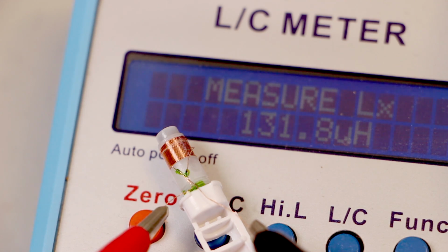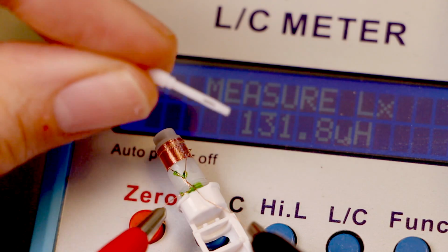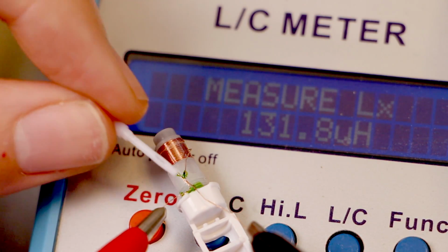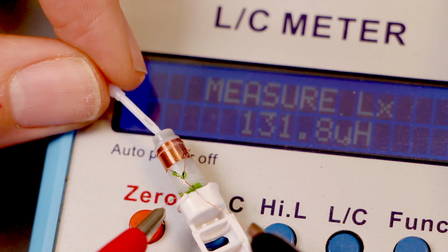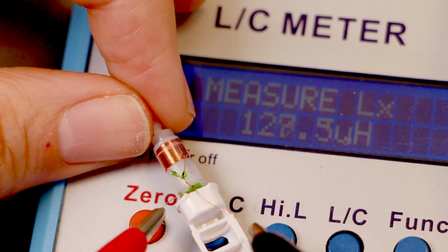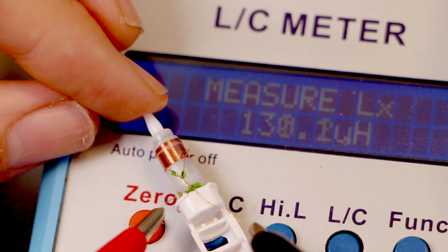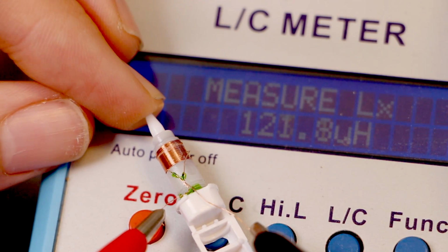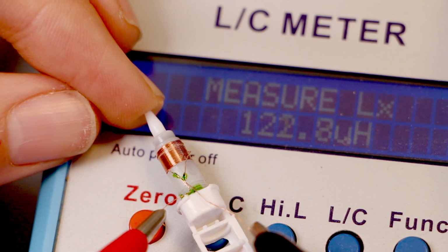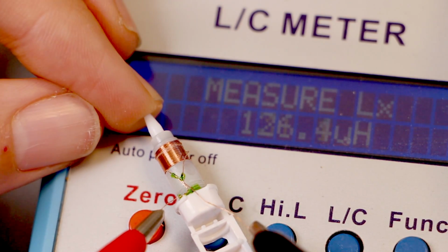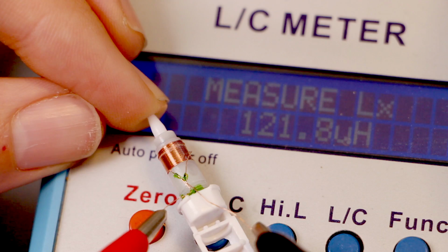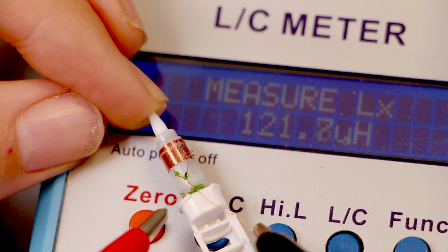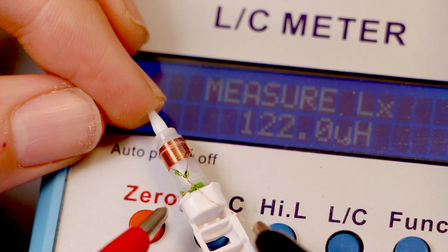Here I have the coil removed from the rest of the pen circuit and connected to a meter that measures its inductance. The pen nib itself is made of plastic and doesn't affect the inductance of the coil, but the pressure from the nib moves a small ferrite core inside the coil that changes its inductance. This small decrease in inductance decreases the amount of energy that this stores in the magnetic field, and it slightly increases the frequency of oscillation because there's less energy that has to be converted before the oscillation can continue.